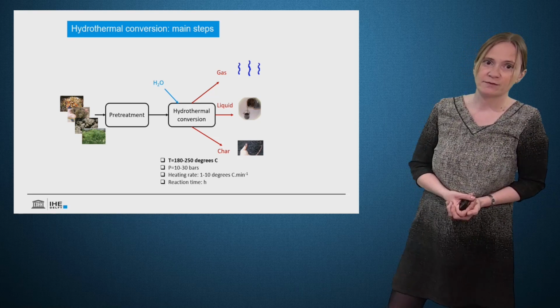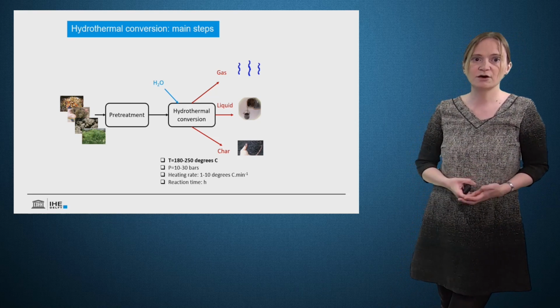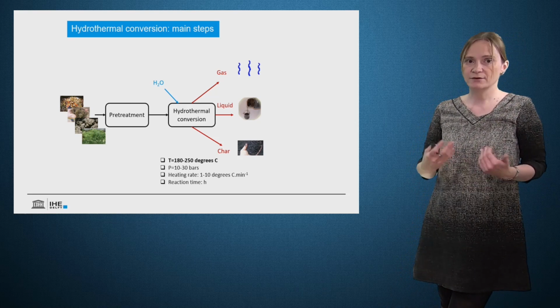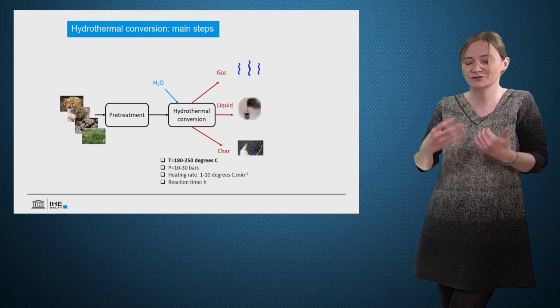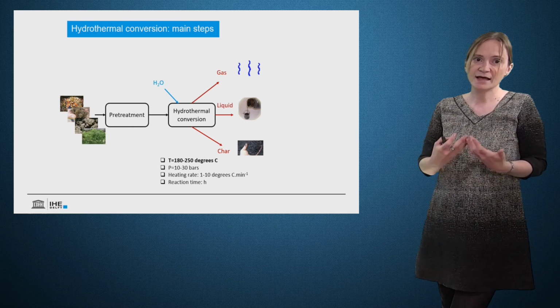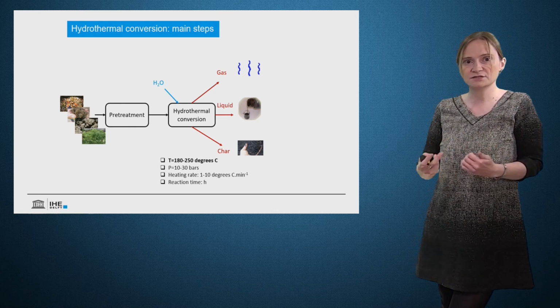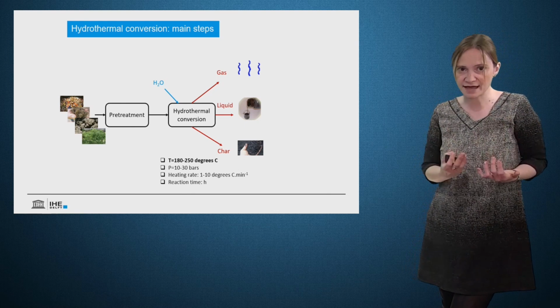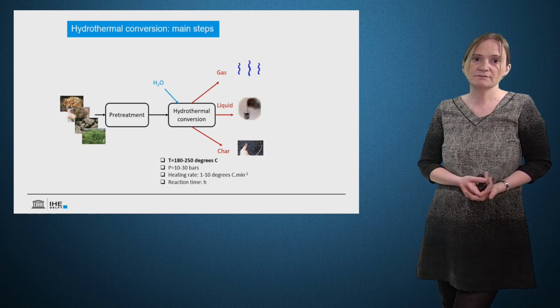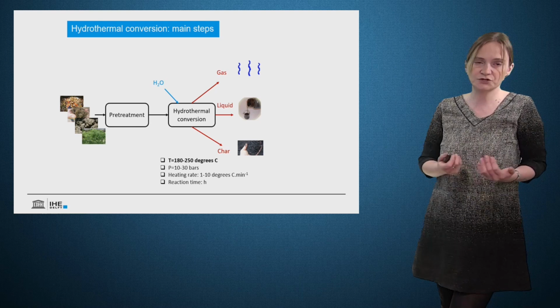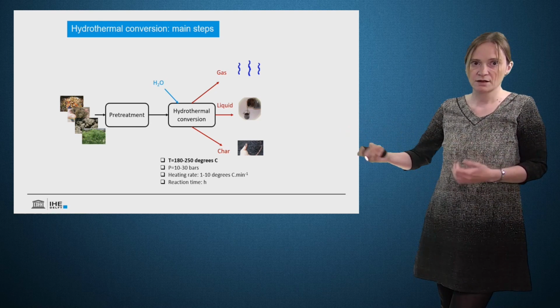So what is hydrothermal conversion? It's a reaction of the material that is immersed in water under high temperature and an autogenous pressure. As for pyrolysis, under these conditions, the material releases some gas, such as carbon dioxide, as well as liquids, and gives rise to a solid called char or biochar.